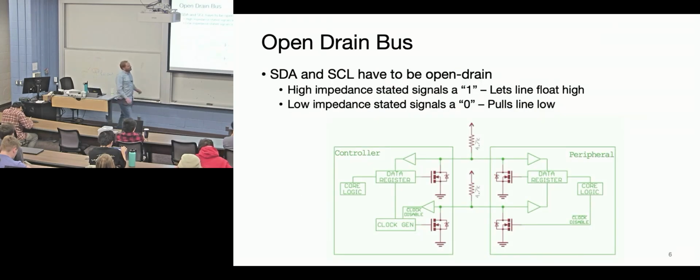And so here in this example, this is just the internal wiring. What do we have? A clock generator. This clock is going to this MOSFET, so this is open drain, and then it's going to pull this line up and down. This one's going to receive that data, and if it wanted to, it could talk back on the clock. Right now it's disabled, but it could if it was set up as a master, but it's not. And data is bidirectional, so the clock's not bidirectional, but data is. Here data is being sent out, pulling that line down, and this inverter is pulling that data into the data register. When it's this guy's turn to talk, he'll pull this line down, and they talk back and forth.